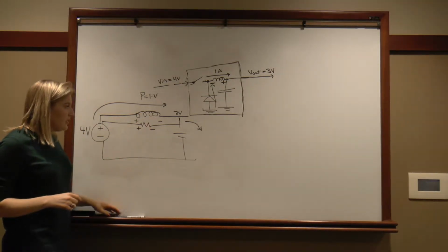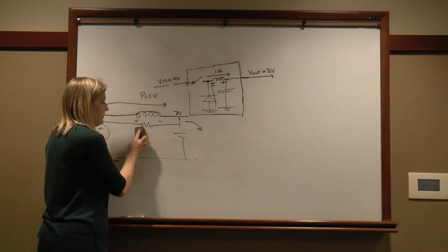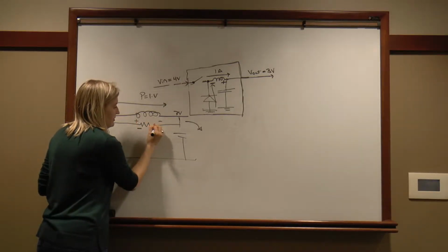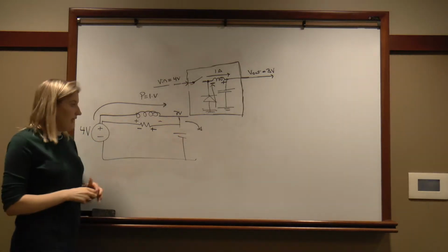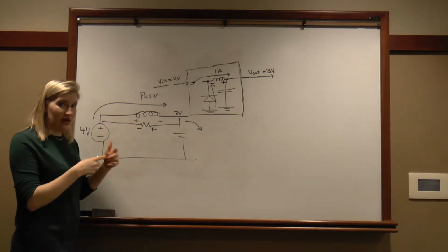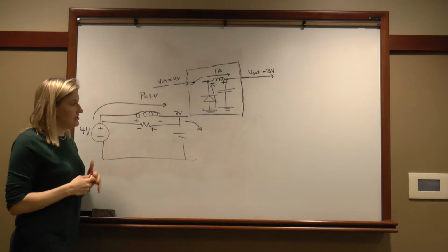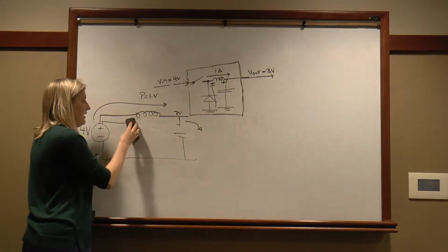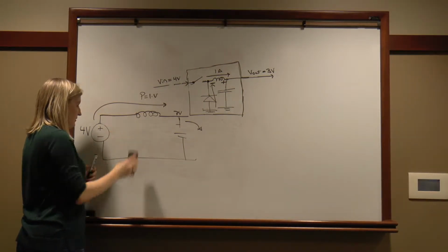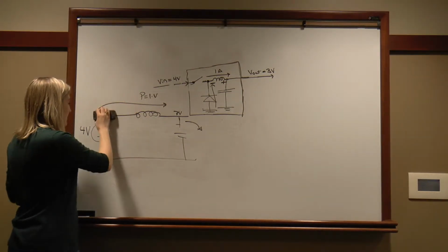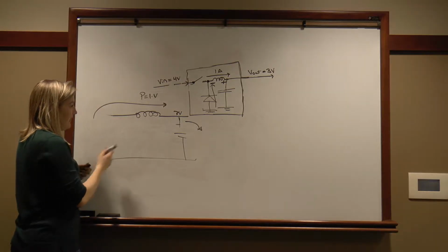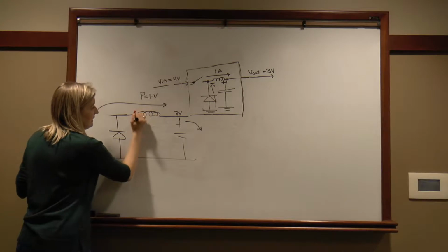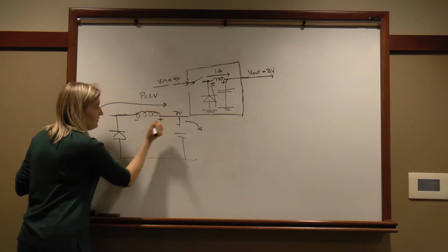Now, you never see the voltage of a resistor go this way, where you've got the resistor releasing energy, right? Where you have current going this way and a voltage gain across the resistor. You don't see that, but you do see that in the case of an inductor. When we open the switch and we take away our input voltage and we provide another path for that current to travel in, we actually see the polarity of the voltage switch.